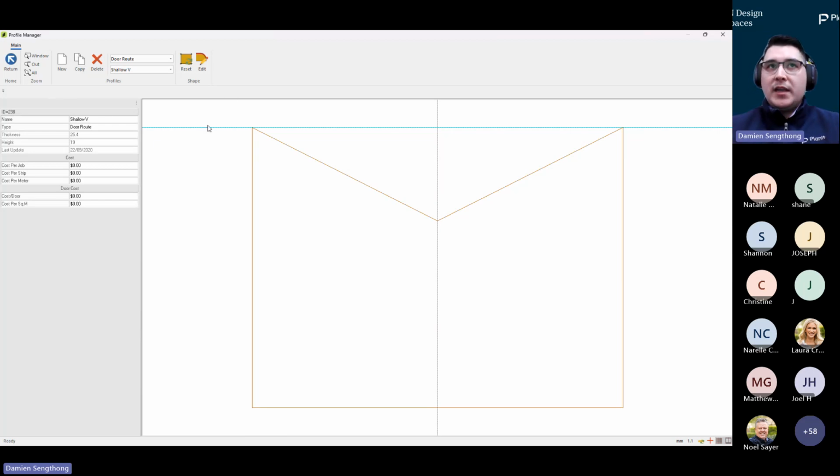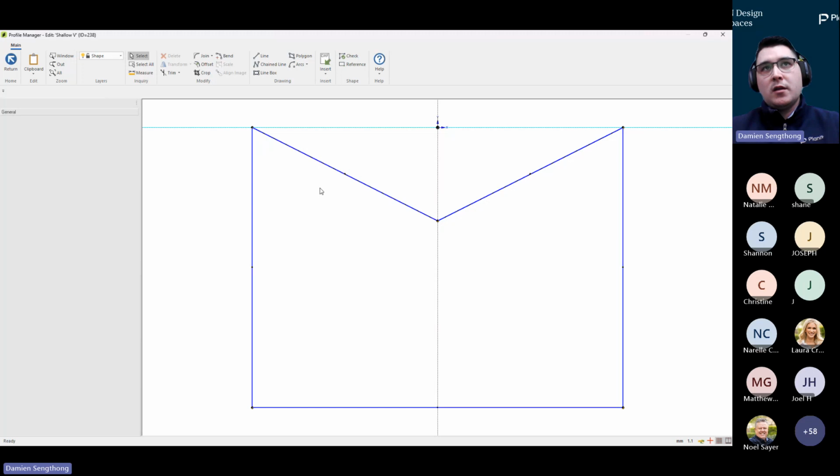You do have the ability to create your own inside Cabinet Vision Design. So across the top, when you select a profile, you can edit an existing one. Then it does supply you with the drawing functions for you to create the profile that you need. If you have a DXF of the particular profile that you are wanting to use, you can also insert a DXF file, whether it's an image or a DXF file itself. And then for anyone that's shaped a part or a cabinet in Cabinet Vision before, you all would be familiar with the options and how the lines join up.